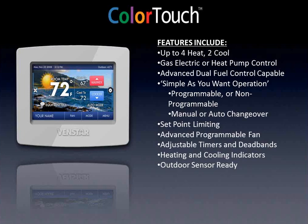And this stat does support outdoor air temperature sensing. Like I said, you need that for the dual fuel changeover. It also does display it on the stat. As you can see up in the top right-hand corner, it does display the outside air temperature. And then the commercial one would do the same thing. Or commercially, you can use a remote room sensor on that guy and have the thermostat back, say, in a manager's office, but then have little sensor squares, little cubes out in the space in a restaurant or something like that.